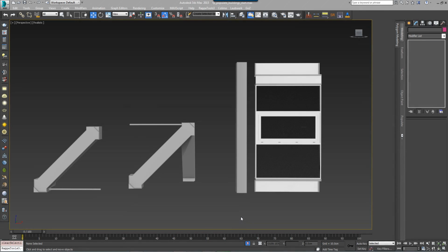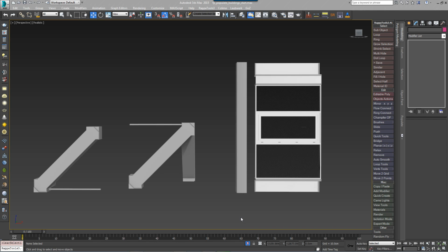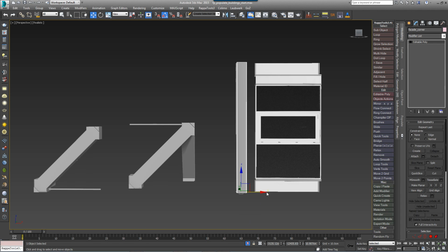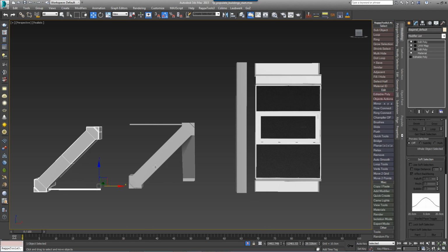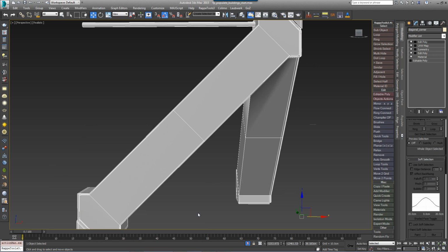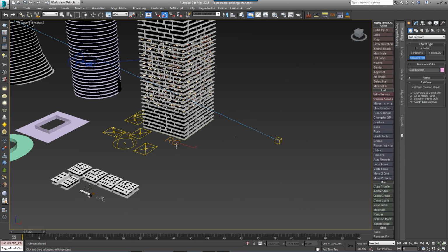As a bonus to round up this tutorial, let's create a couple of RailClone styles to add a facade to this building. To maintain compatibility with the light version, we've split the facade into 2 separate RailClone objects, but they could easily be combined if you're a pro user. These styles each use 2 segments. For the windows, it's a corner and the window itself, and for the support bracing, a single diagonal and a corner. The aim with these styles is to maintain instancing support as far as possible. So to ensure this, none of the segments are sliced or bent, and the corner segments have been pre-sliced before adding them to RailClone. Here's how to use these to construct a style, and we'll start with the window.